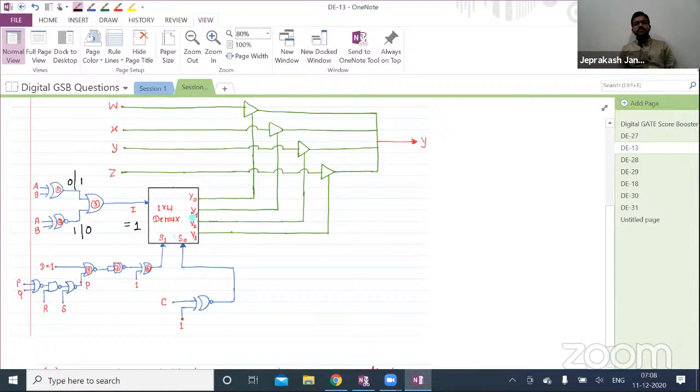Okay. Now, this is the demux. The functionality is decided by the selection lines, right? Whatever the input is, this particular input will be connected to one of the 2 power n outputs based on the selection values. Now, just observe. Here you are having NOR gate. One input is 1, whatever may be the other value. Irrespective of that, what is the output you will get here? Zero, right? Yes, very good. Very good, Srinivas. Yeah, 0.